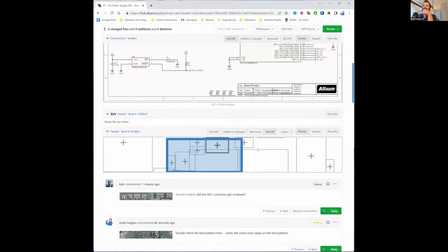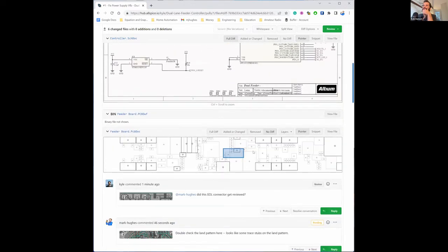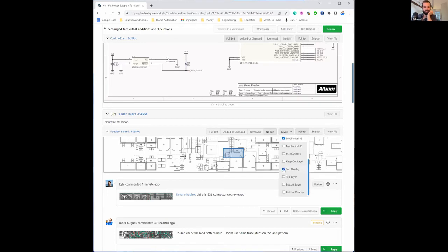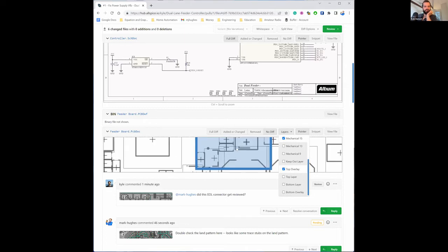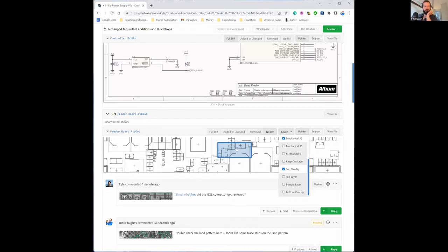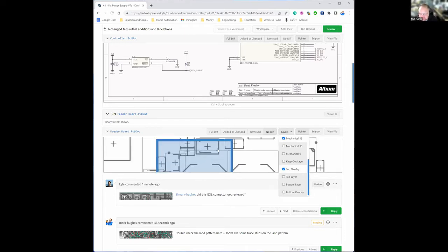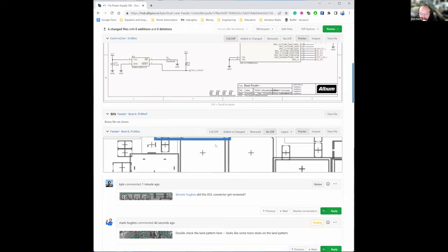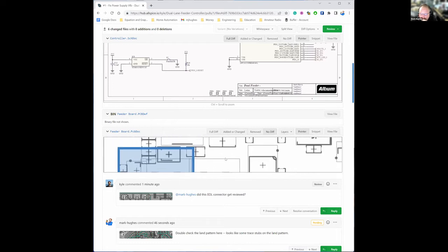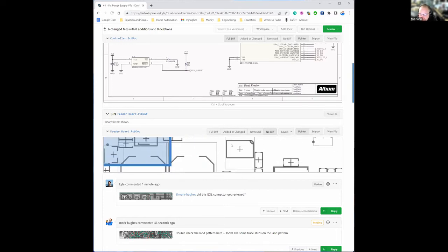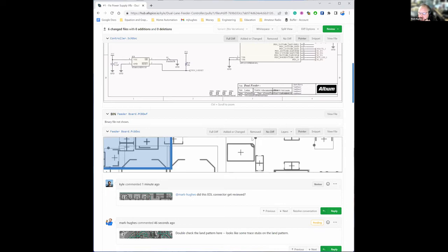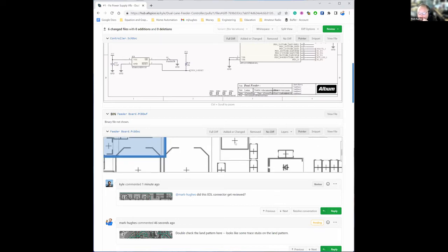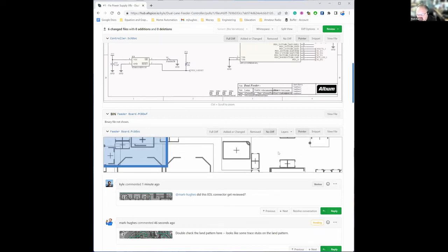Like the courtyards and underlying components I'm looking at, if you toggle the overlay on, you can kind of see maybe a little bit more where they had intended the components to be. And some of them look like they just don't quite line up with their underlying ones. So an update to these components would be helpful. It could just be a library issue, and it could be that I'm looking at the wrong thing. But if these are in fact the component outlines, that is a really big courtyard for whatever the heck that component is.